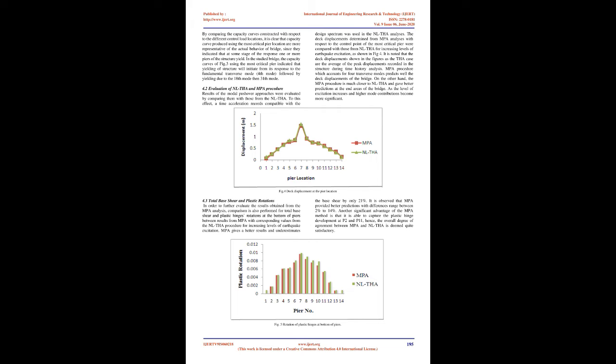The moment-rotation capacity of the plastic hinge is defined based on the stress-strain relationship of the section, considering the confinement effect from transverse reinforcement. Bearing is modeled using a link element in the SAP2000 Nonlinear program. To accommodate soil-structure interaction, each pile is modeled as a spring with 6 degrees of freedom to represent translational and rotational support. To perform analysis of the structure, the next step after modeling is applying loads.